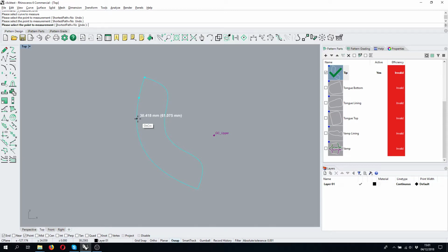So in this case I measure 3 centimeters, and another 3 centimeters, and then 3 more, and then 3 centimeters, and I can divide this using this technique, and I have my various points that are then added to my model once I accept. I have the total length measured, and I have my points here that I can use as a reference, and then I can delete them.